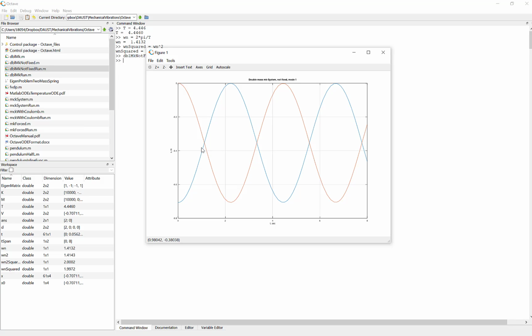I've basically done exactly the same thing that I did before, where I pulled both masses equally apart. Well, I pulled them apart here too and let them go. So it's basically the same phenomenon, but instead of oscillating around 0, I'm now oscillating around the average of the two initial displacements. So we've excited the second mode, but at a different location than we did the first mode.